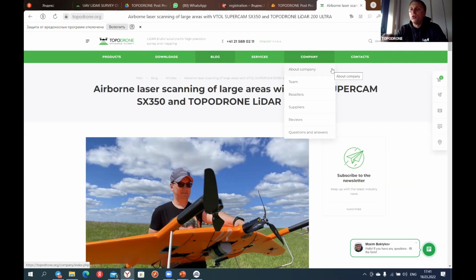Yes, from this point of view, I didn't say it during the presentation, but when Victor shows us how easily you can remove vegetation and how clean a terrain level you can get, and how easy it is to understand obstacles or objects situated closely to power lines, it's amazing to use LiDAR. You will definitely save your time in the field. I wouldn't say that photogrammetry is not possible to use for power lines, but there are a lot of advantages, which Victor already said and I already said.